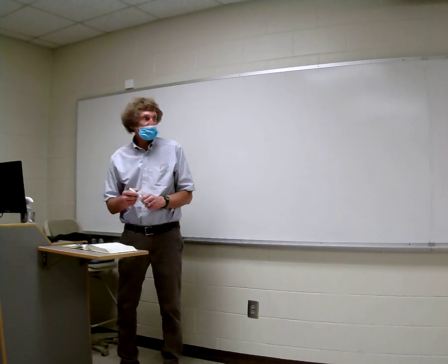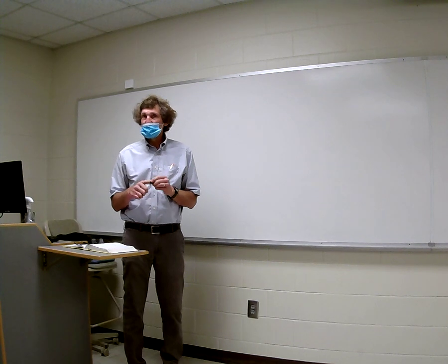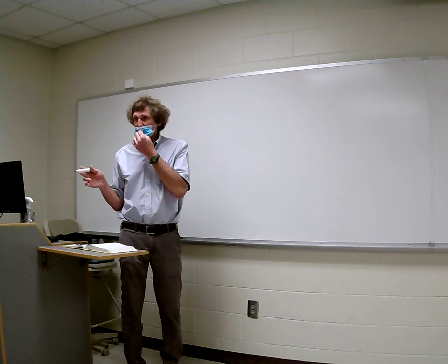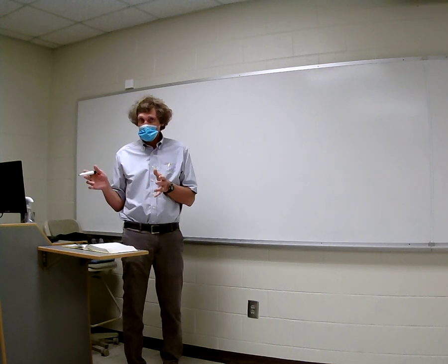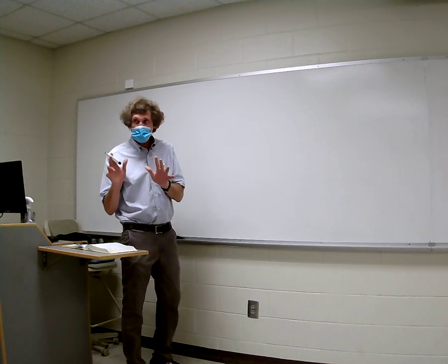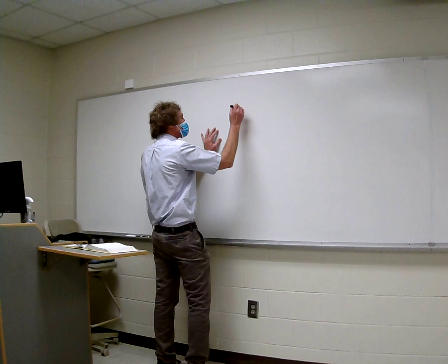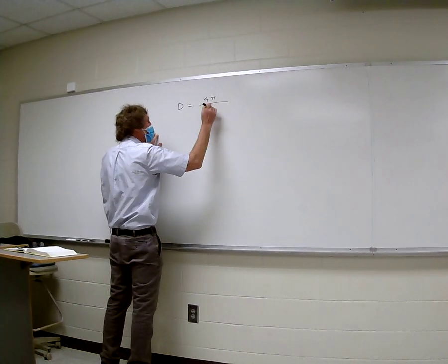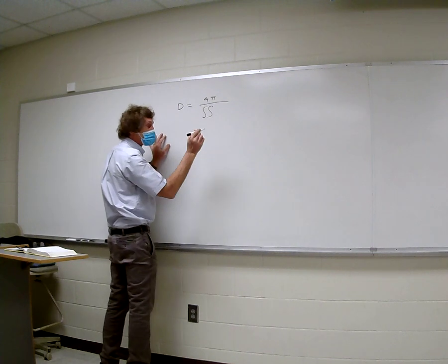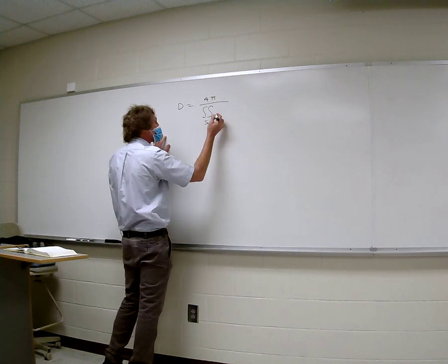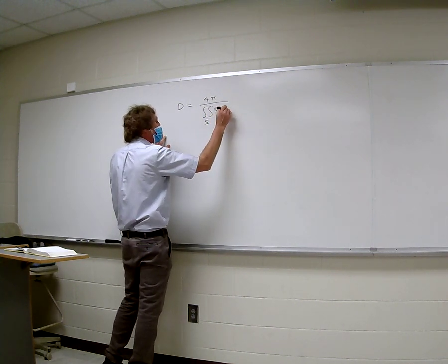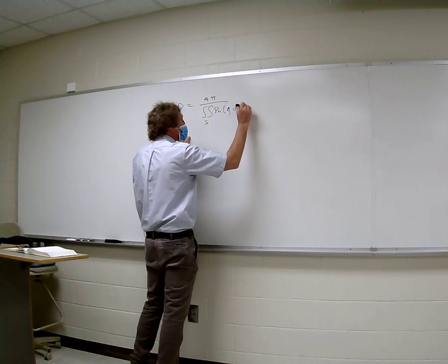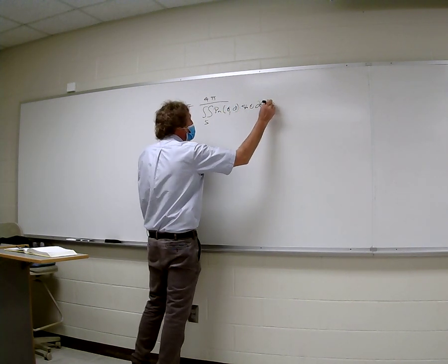Now, about gain, I just want to put everybody on the same footing here to make it clear about it. Gain is a measure of the focusing power. We know the mathematical definition for gain, or directivity, right? Now, I'm going to put that up here. I'm going to draw something. So I know directivity here is equal technically to 4 pi over the integral over the surface of the normalized power density of theta phi times the sine of theta, d theta d phi.